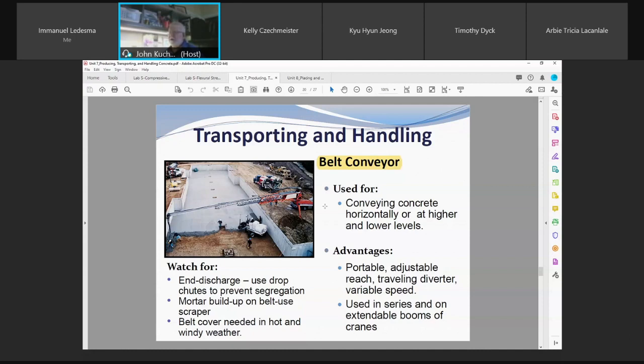Okay, so we dumped the concrete out of the ready mix truck into 1 pump. Then that pump extended his boom as far as he could go. And then here, with this chute, he pumped it into the next pump. Just like a ready mix truck would dump into the hopper of the pump, we were dumping into the other pump from this pump, and then he boomed over to the other. So we basically had 2 pumps in tandem.